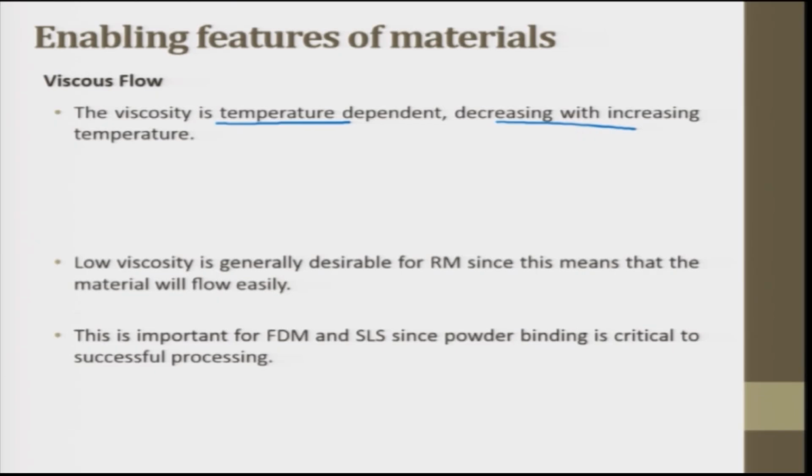Both polymers and liquid metals follow a general relation, where this eta can be put as eta naught into exponential of Q by RT.